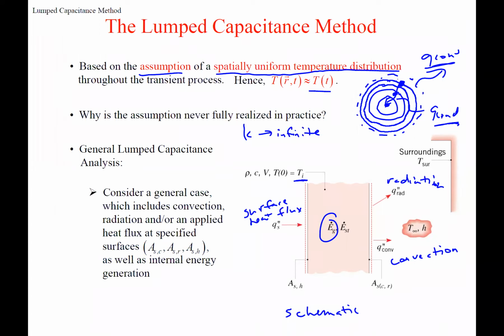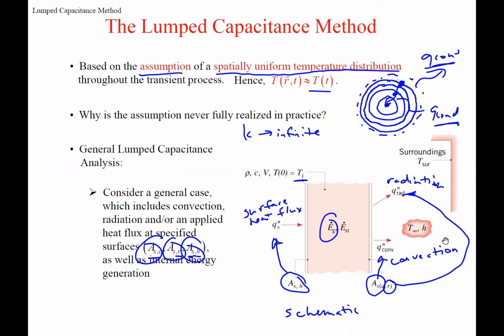And we have an area that goes with each of them. We're not simplifying, we're keeping it very general. So this surface area goes with the heat flux. There's one surface area with convection. There's another with radiation. That's why you have 3 surface areas. They're different, so maybe you have radiation on the right wall and heat flux on the left wall, so that could potentially have 2 different surface areas. So it's general. All right.